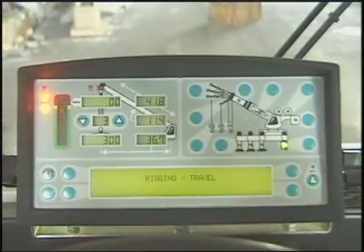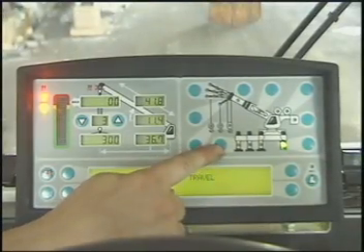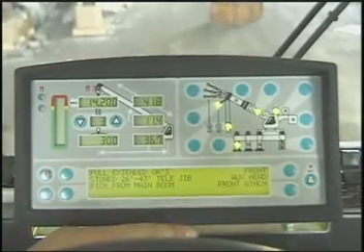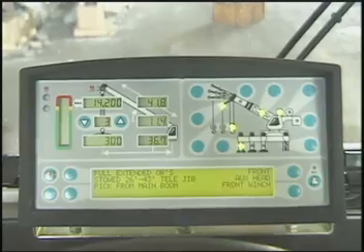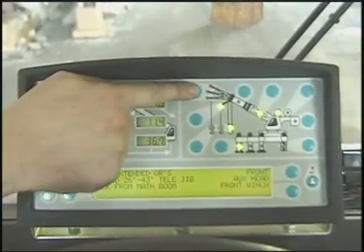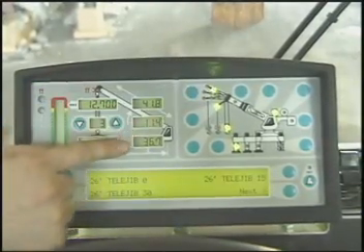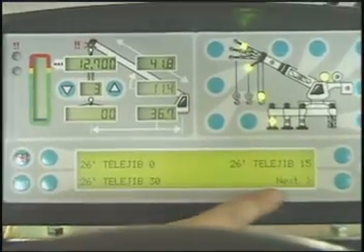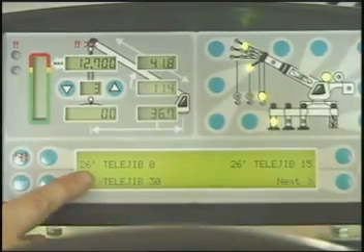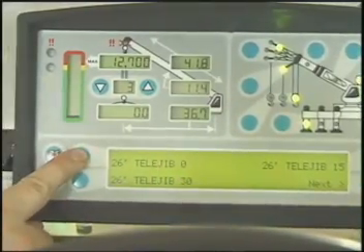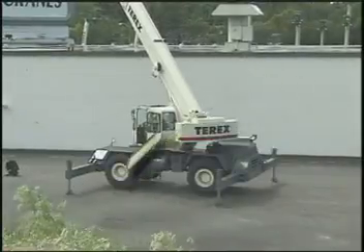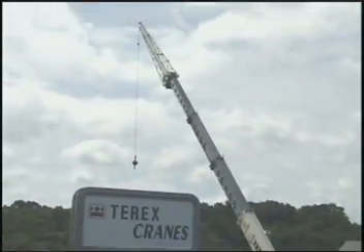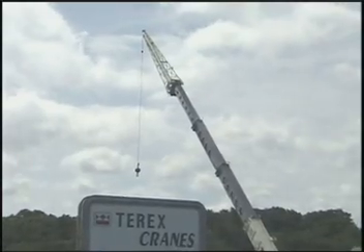The first thing we need to do is press the fully extended outrigger button. Now we will erect our 26-foot telejib. Press the jib button and select 26-foot jib with 0-degree offset. In this position, we can't reach back far enough onto the roof, so we need to extend the stinger and set the jib to 30-degree offset.